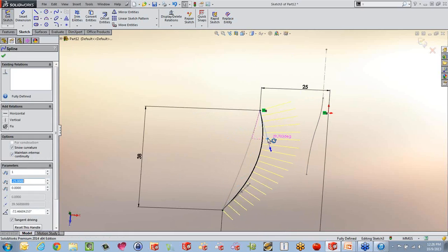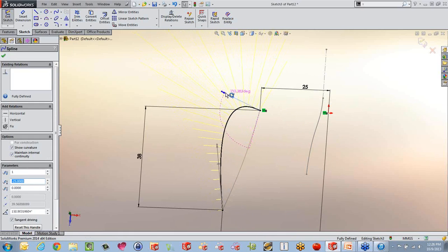What will show these small lines, and these lines show us how the spline is reacting, how smooth it is. And this is for if you are making consumer products. You can't actually see this in real life, but this is what you see if you're standing out in the parking lot and you look down the side of your car. You know how when you look down the side of your car, you see the reflection going smooth all the way down the side of the car. They're controlling this by making splines that are not cutting into themselves, that are not sharp like this. They're making sure that the curvature is smooth.